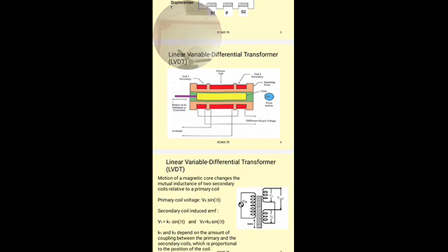The AC voltage output from an LVDT indicates the position of the mobile core. 0 volts means the core is at the center. The further away the core is from the center position, the greater the percentage of input excitation voltage will be seen at the output. The phase of the output voltage relative to the excitation voltage indicates which direction from the center the core is moving.